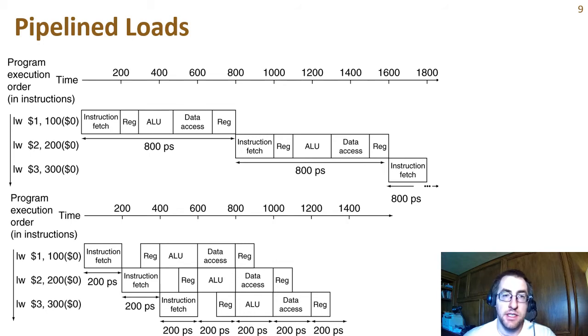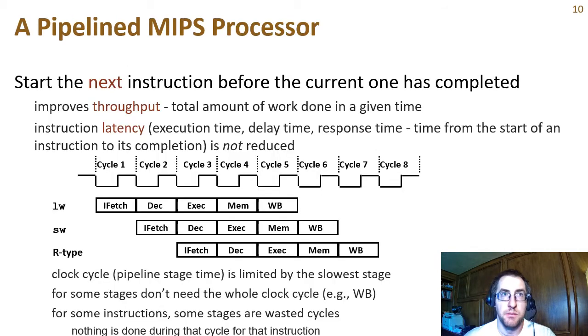We'll come back and visit that again later, but the important piece here is that we won't need to be reading and writing the register file at the same time. So the register writes happen on the falling clock edge, and the register reads will happen on the rising clock edge, the high level of the clock cycle.